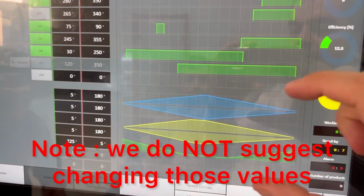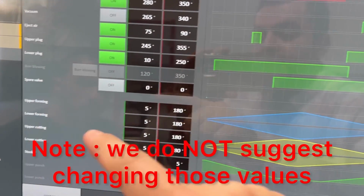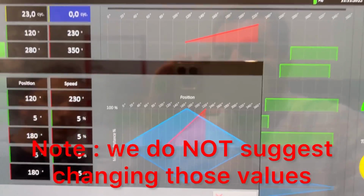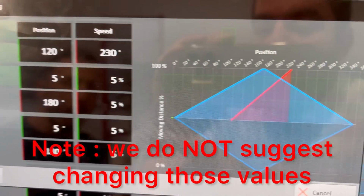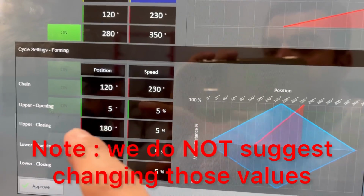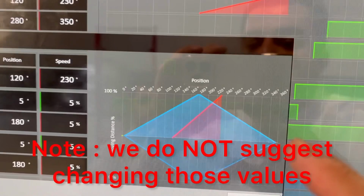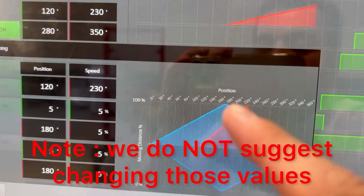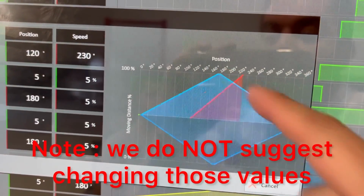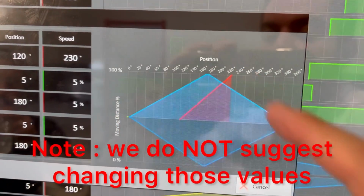Here, in the lower part of this cycle page, we have the upper forming and lower forming moving blocks. So it will start moving here from 5 degrees. It will start opening and it will start closing from 180, and again until it reaches the end. So from 5 to 180 and from 180 to 360. So it's opening here, closing here. Again, opening, closing, like that.